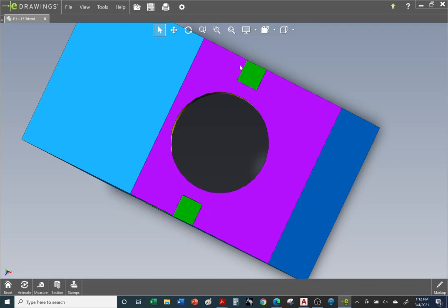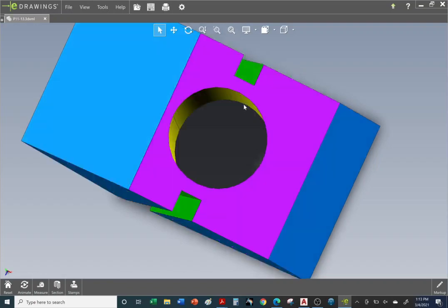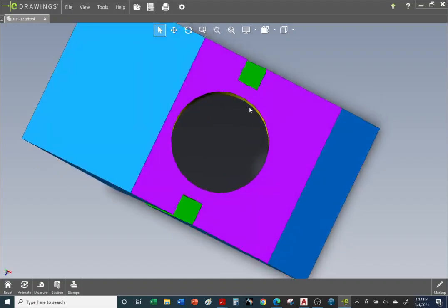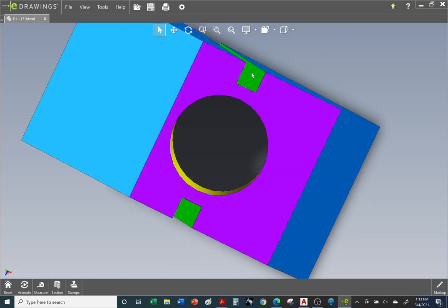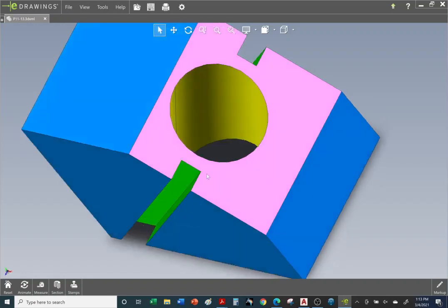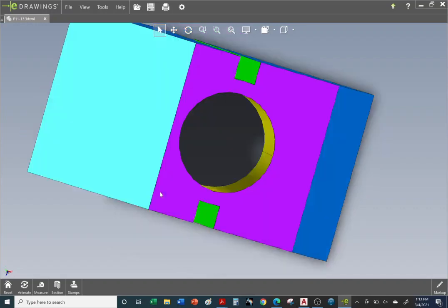We have our visible object lines for the slot. Notice how we have a visible line here. So this one's not open like the previous auxiliary view. It was open this way. From this perspective, it's closed, right? So this is one solid visible object line. So now we need to represent the exit with red hidden lines on both sides. And we need to represent it sliding downward at an angle.